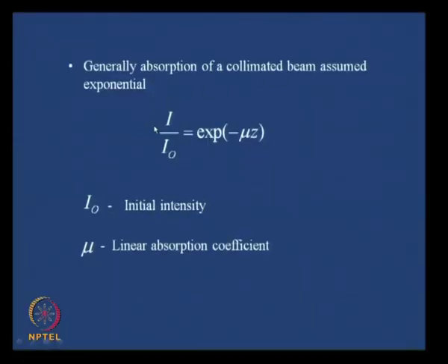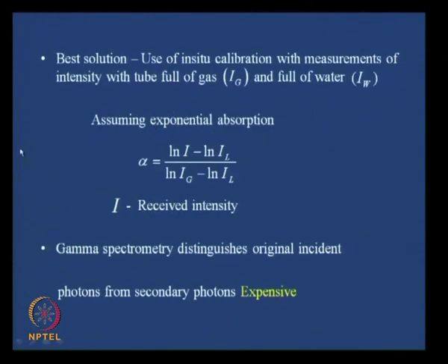Now, we know that the relationship is exponential. As I have shown you in the previous slide, in the transparency that I have shown you, this particular relationship is exponential. So, if this exponential relation has to hold, then we should get the void fraction from something of this sort, isn't it?